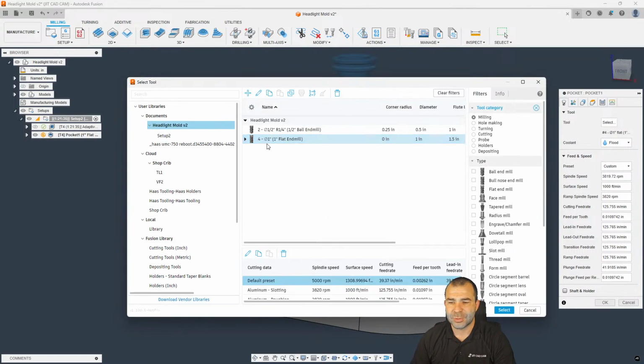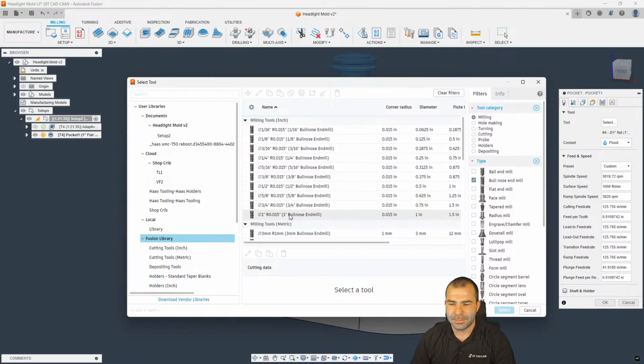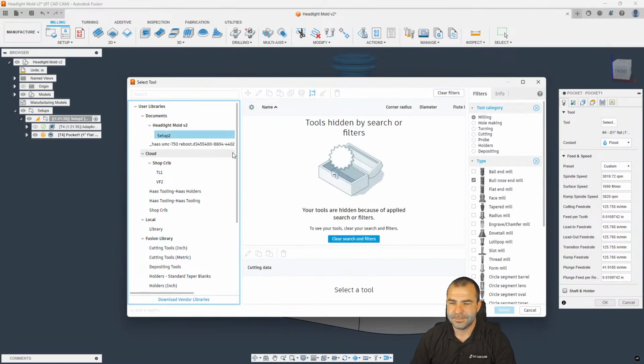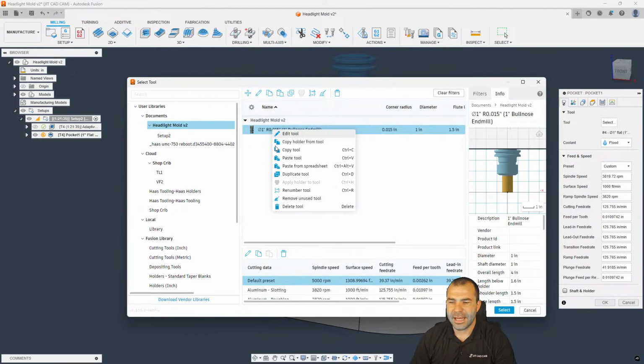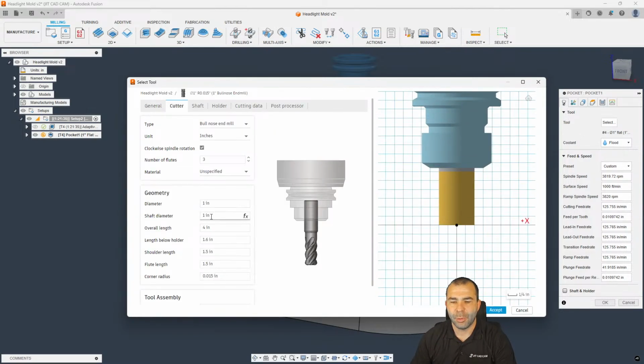But what I would look at on a part like this, if we look more into pocket clearing, is I'm going to go ahead and swap out this tool. We're going to keep with the 1-inch tool idea, but I am going to go with a bull nose end mill this time. And what we're going to do is copy this, and then we will be making a quick change to it. If you've ever used a high feed mill, a high feed mill is going to come more with that idea of your flute length being closer to 0.375, or if you're using an insert mill, you're going to have a corner radius on that if the idea is you're going to remove a lot of material. So I'm actually going to bump this up to about 60 thou.